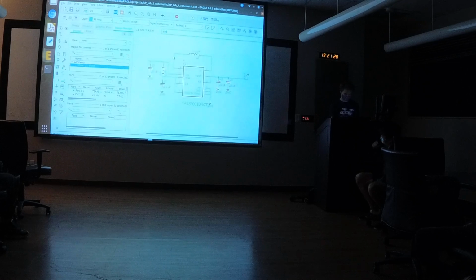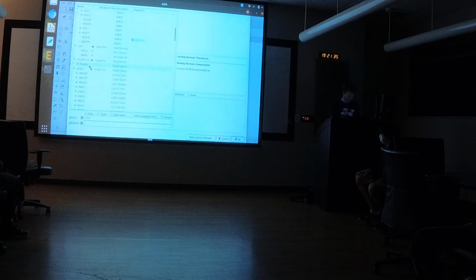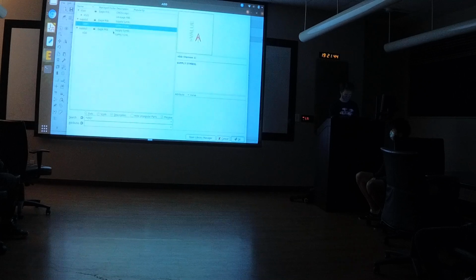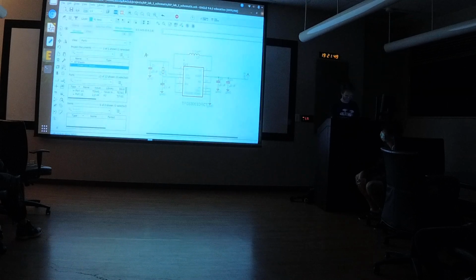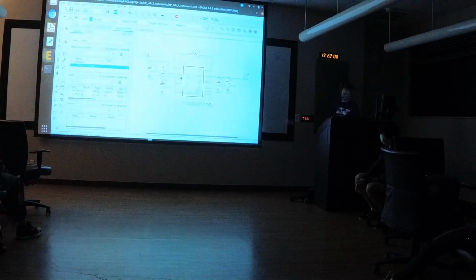Okay. And then our input voltage is going to be variable. But that being said, we can safely assume that it's going to be 5 volts, or less than 5 volts. So we're going to type in VDD. Oh yeah, they have a symbol for that as well. So then we go to supply. This one's really ugly, so we're going to go with that one because that looks cool. As long as you keep it consistent, it'll be fine. You can also choose to use your own labels, but I think it's a lot easier to use their predetermined ones. Right, and then of course we want to merge net segment N4 and supply net VDD.